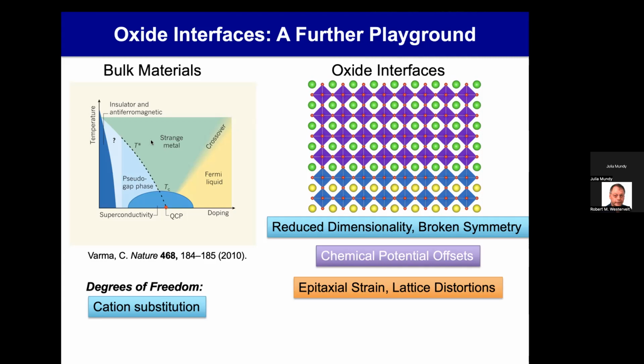And that's really cool because these are ceramics. This is basically like pottery that we're making, that kind of material. And if you take pottery and you try to pull on it, you can definitely not stretch it 10% before it cracks, right? I mean, this is a mechanical engineering question, but it's not going to stand up. It's not even going to get 1%. You're going to get a fraction of a percent that you can actually expand it before you just have fracture, okay? And compressing it as well is also tricky.